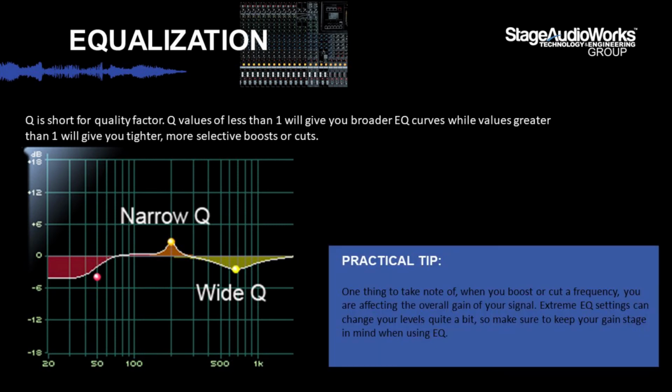One thing to take note of when you're boosting or cutting frequencies: you are affecting the overall gain of your signal. Like we spoke about gain structure earlier, it might not be worth spending forever doing this perfect gain structure before you've EQ'd, because once you start boosting and cutting frequencies, you are directly affecting your gain structure. So be sure to keep your gain structure in mind when using EQ.